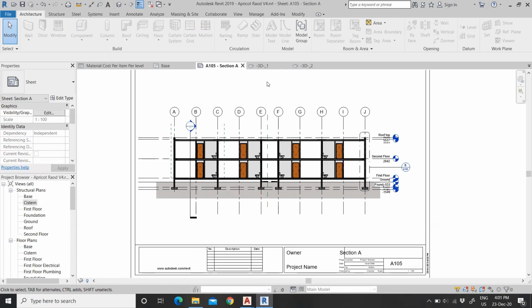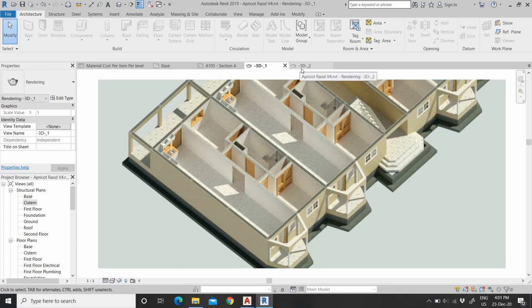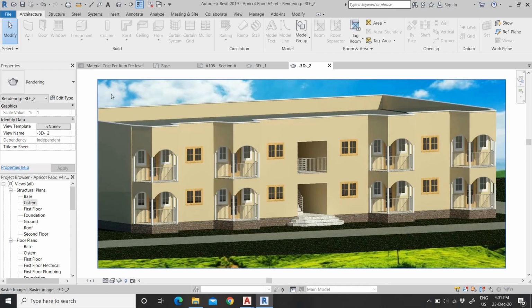I just did it in Revit and then I exported it to DWG format that I can then import into my AutoCAD drawing as an Xref. And then I can further add leaders and dimensions in AutoCAD how I normally do. So then you will have basically the same outcome, a drawing, but just using the model from Revit. So guys, without further ado, let's get into this video.